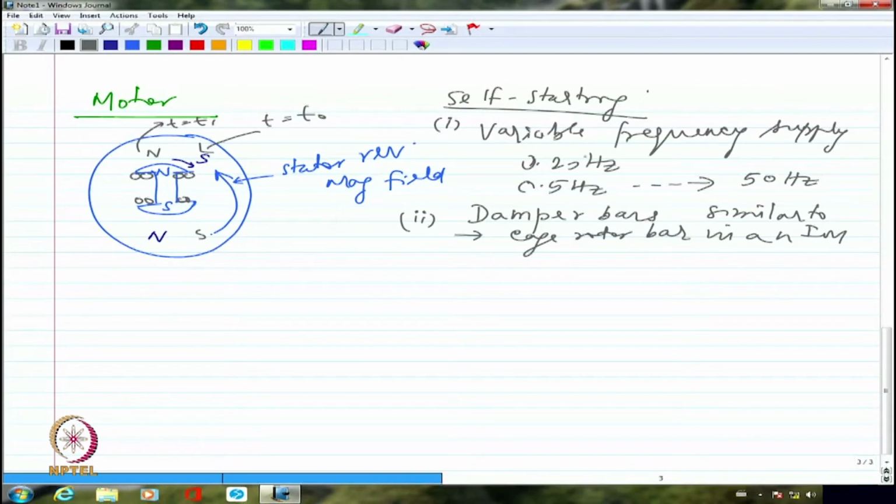Every time there is some disturbance, some speed coming down or going up, maybe a frequency fluctuation, maybe some kind of load fluctuation, if the speed fluctuates, at that point the damper jumps into action. The damper will not have any action when the speed is synchronous speed.